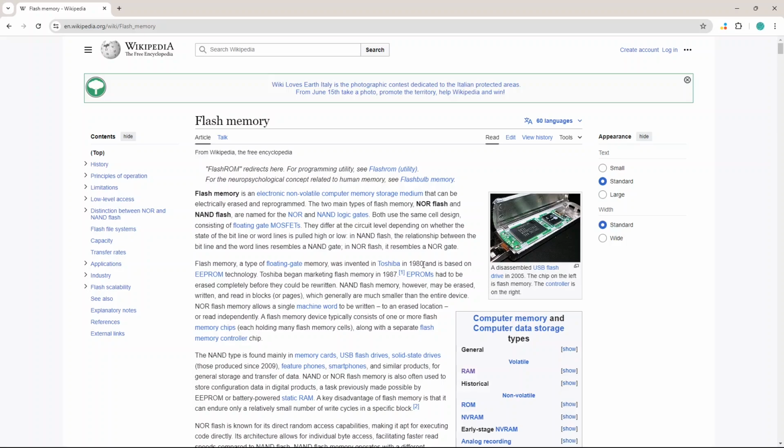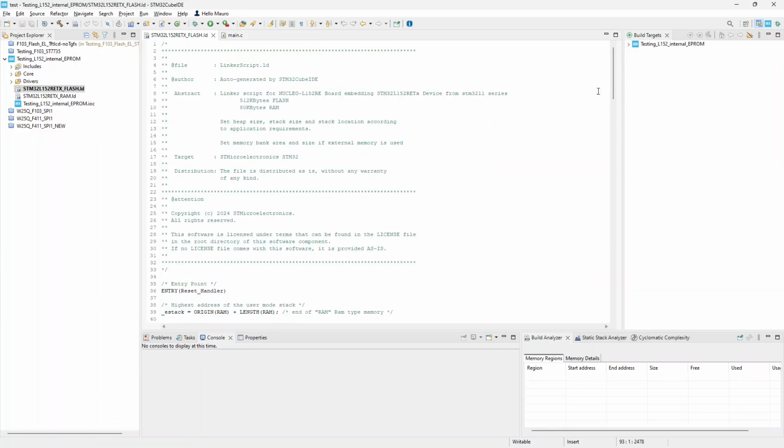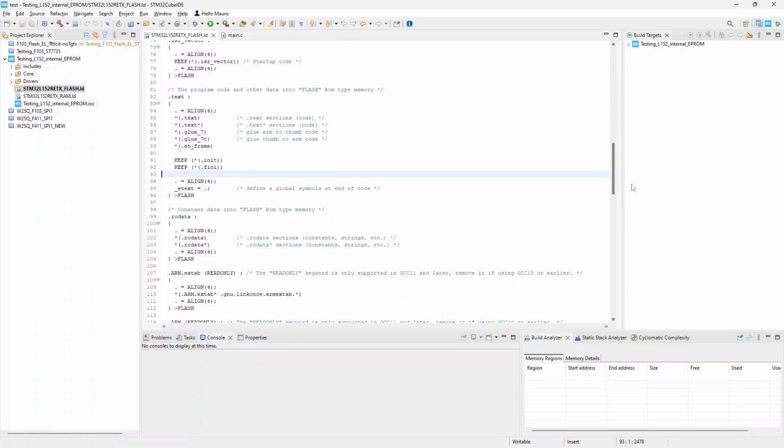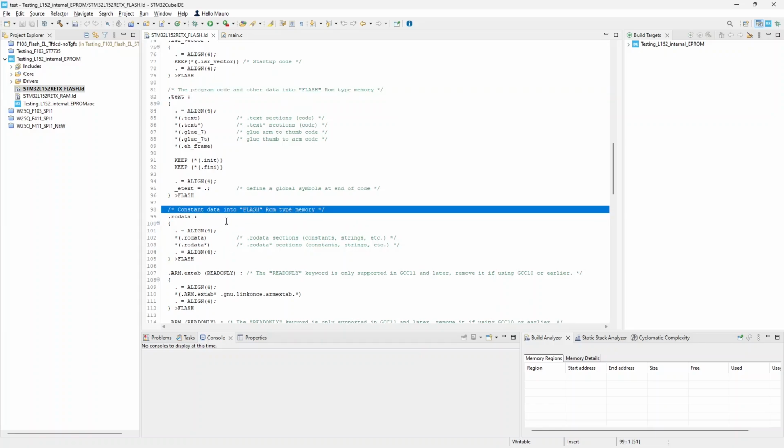We have seen in other videos that there are two, let's say, types of flash memories. Two main technologies, NOR flash and NAND. Microcontroller flash memory is a NOR technology, as, broadly said here, with details in other videos of my YouTube channel. That type of flash allows a faster random access, allowing the microcontroller to run programs directly reading them from flash. So, program and constant data are saved on flash, and we can reset or power off the system, keeping safe the data and programs. They can restart when the system is powered back on.